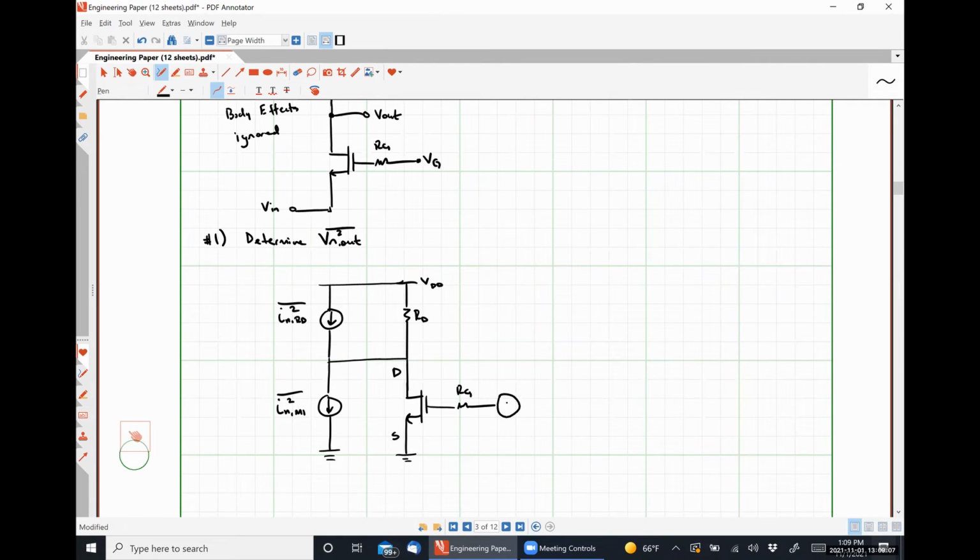And I'm going to choose to represent this noise voltage generated by resistor RG as a series connected source. And my output signal here, VN out. So let's talk about some of the decisions that I have made here. Choosing to put the noise from resistor RD in this configuration makes it obvious that I can add it as being a current source in parallel with the noise from the transistor, which is what we've been doing in all of the previous examples. So that's just kind of making sense there.